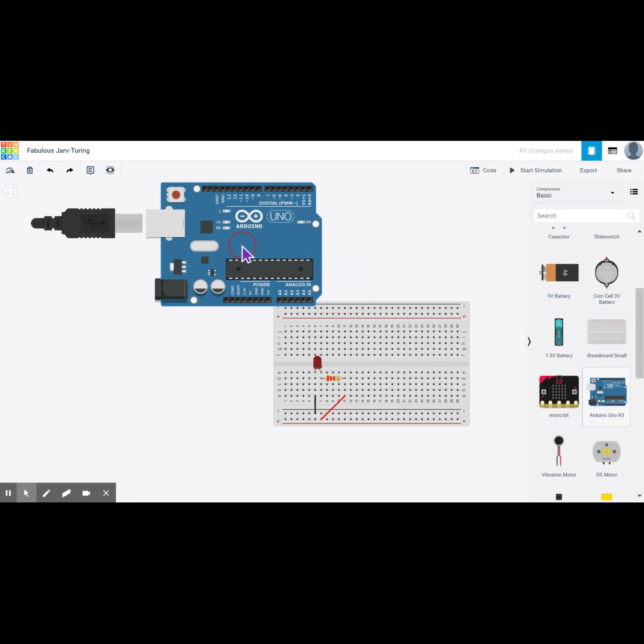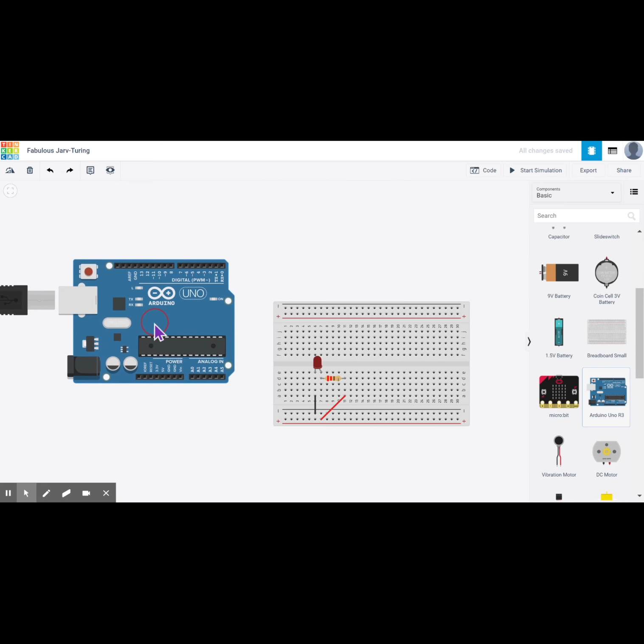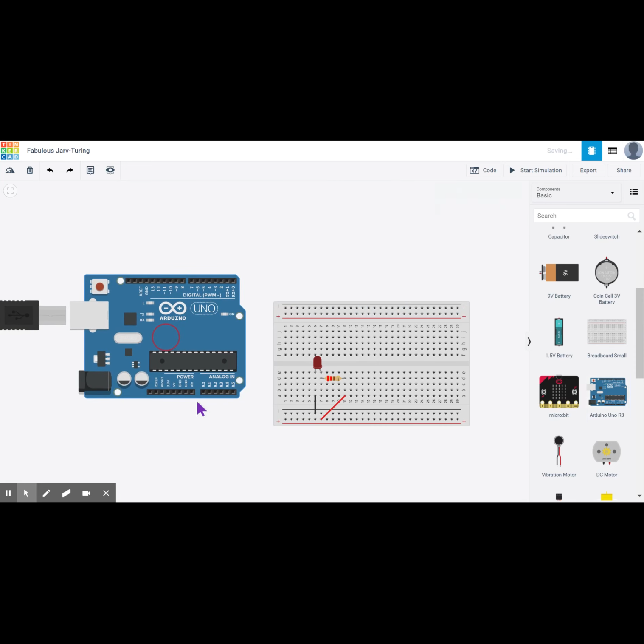We're going to be powering our circuits using an Arduino as the power source. So I'm going to use, there's two ground sources on our Arduino and they are equivalent, so it doesn't matter which one I grab and bring over to provide a ground to my power strip. Make it black. And then 5 volts, we'll go ahead and do 5 volts. We could do 3 volts. I just want my LED to be nice and bright, so I'll give it a little more power.